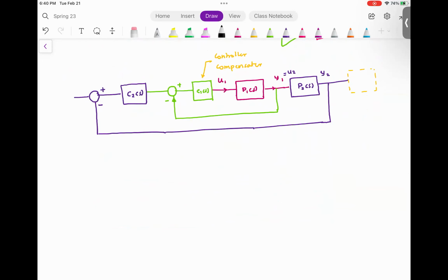Then I'm going to draw this transfer function. Now you have to tell me what this physically represents. This is very important. What does this transfer function physically represent? It's a spring mass damper system. And what is the output? Scaled displacement. Everyone understood this?